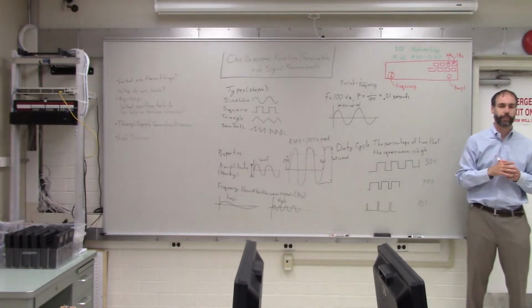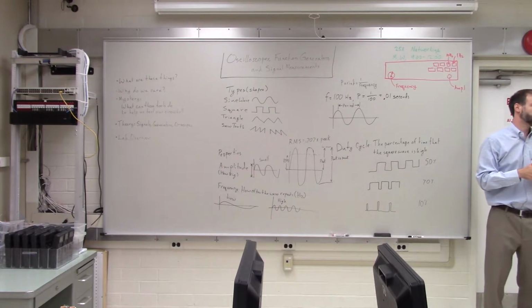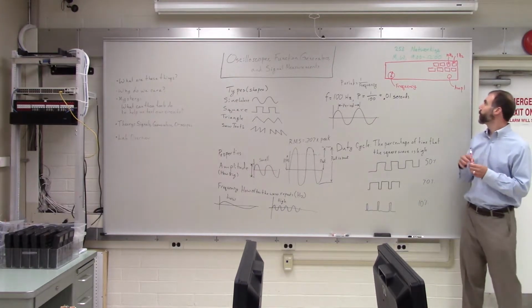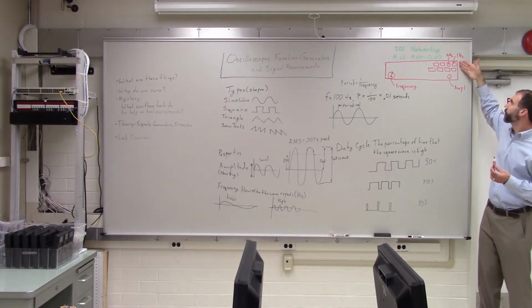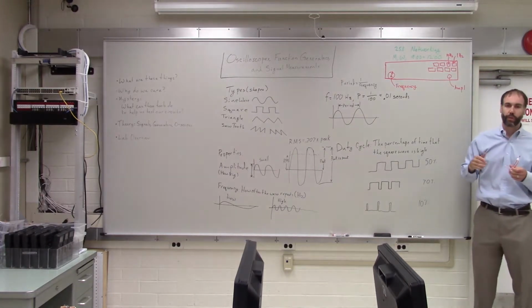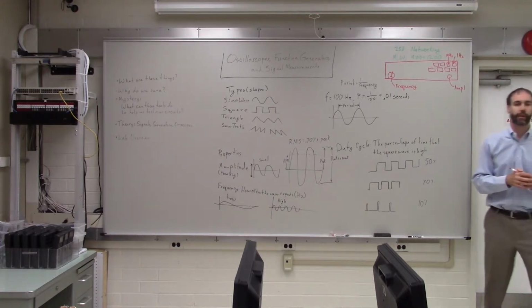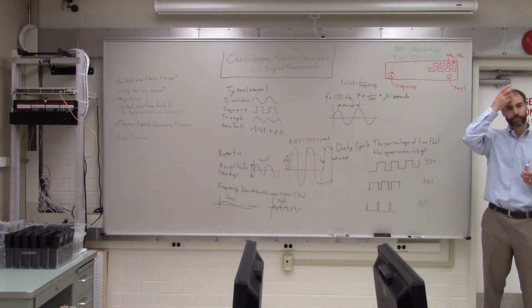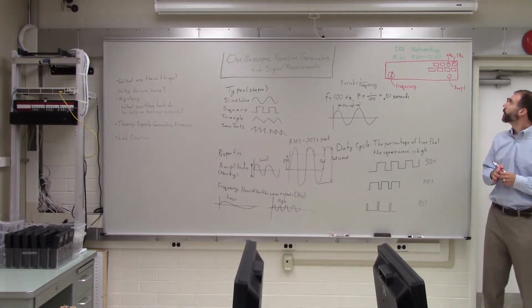Is there a way to get lower than 1 hertz? The actual frequency is the product of the range and the knob. So the knob, I think, goes down to like 0.3 or 0.1 or something. So you could probably get it down as low as 0.1 hertz. Okay. But I think that's the lowest that it goes. Cool. Okay, so that's how you set the frequency.